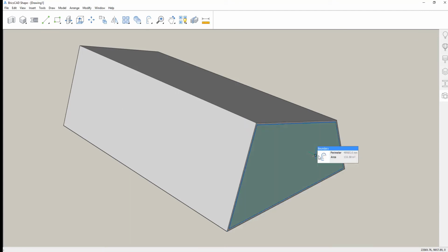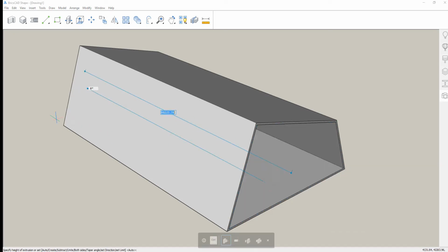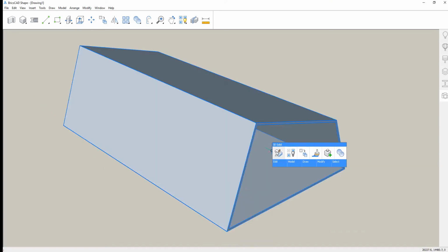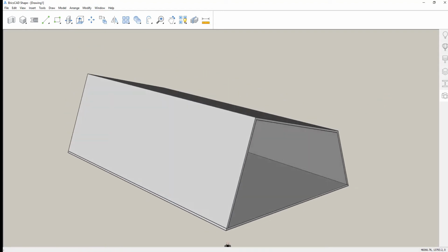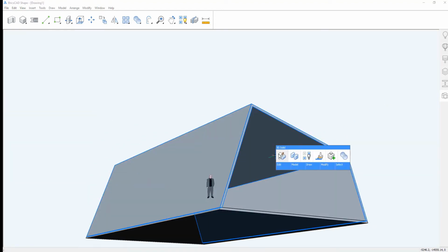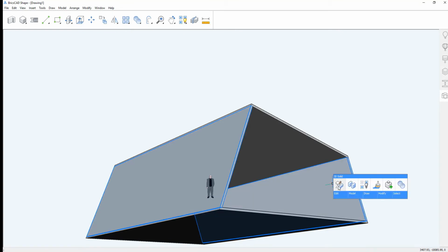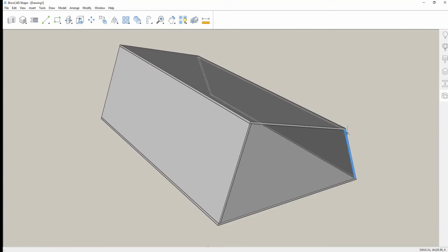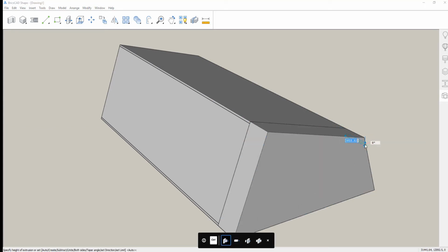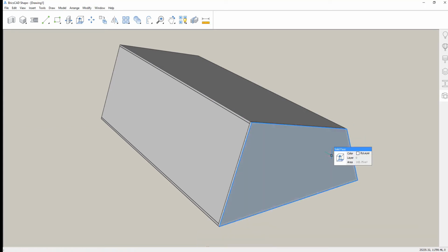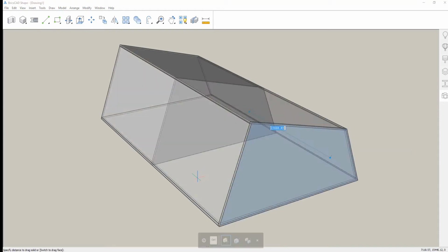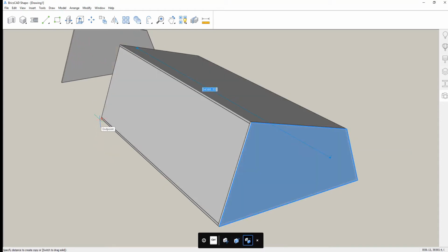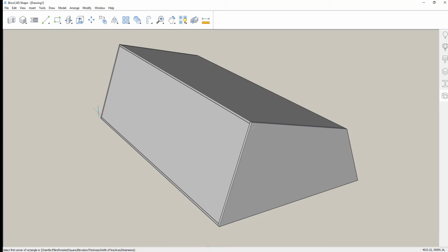Super easy. Select any surface, use the manipulator to copy, rotate, move that surface. Take any existing edge, any boundary, offset it, and use it to drive new solids. Let's split this extrusion up into 4 separate faces. 2 walls, a roof, and a floor slab. Done. Now, next step will be to create the end caps, or the 2 outside walls of our building space. Quickly drop those in.